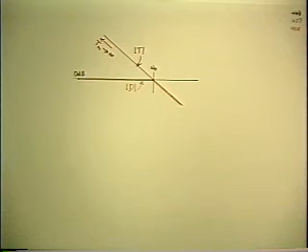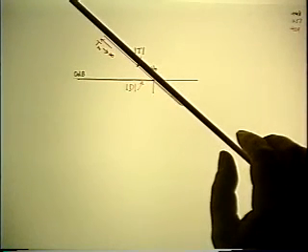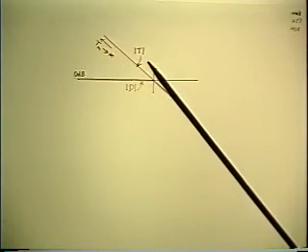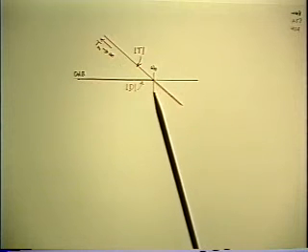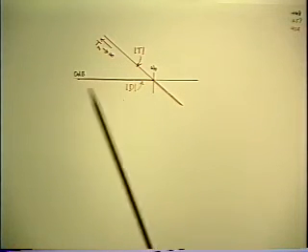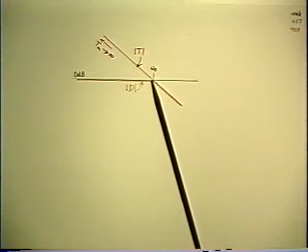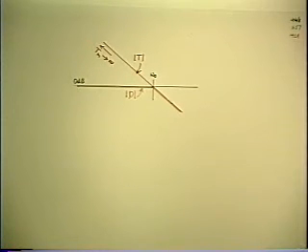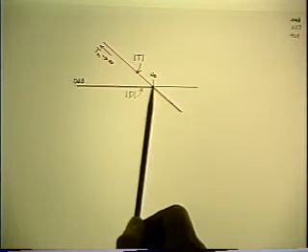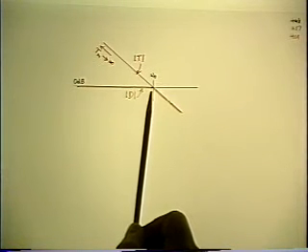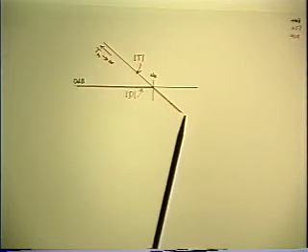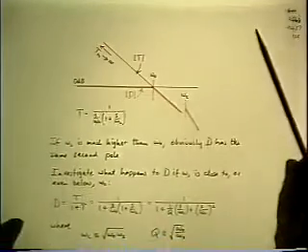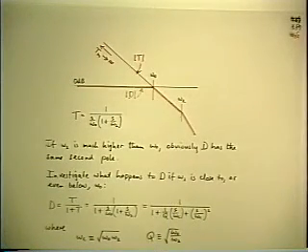So we start with the simplest possible problem, which is a single asymptote for T, and we don't care where it came from at low frequencies. The corresponding closed loop gain, which is proportional to D, is going to be 0 dB with a pole at omega 0. So we've simplified the basic problem, stripped it down to the only essentials we're interested in, which is what happens to the shape of D near crossover. Now we're in a simpler position to start making the problem more complicated in a useful manner, which is to consider what happens if you have a second pole in T.